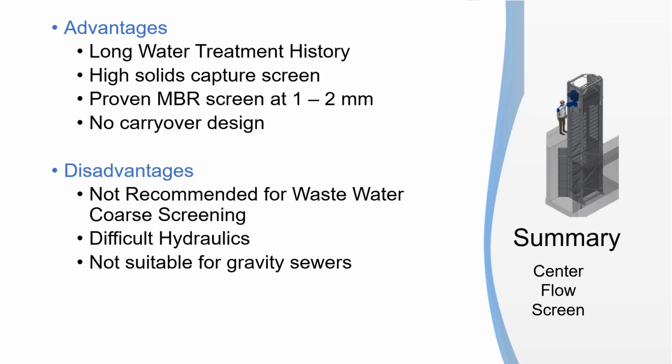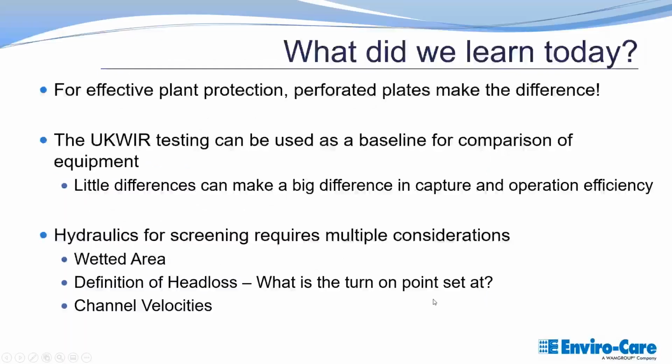Not terribly suitable for gravity sewers simply because if you are using it as a core screen, gravity sewers are going to have the potential of debris landing on here and not being able to be pulled up and out.